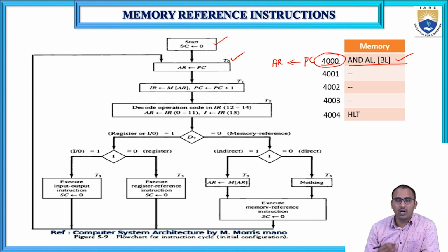After applying one more clock pulse to the sequence counter, it will generate the next timing signal, T1. During T1, the instruction will be placed in the instruction register.